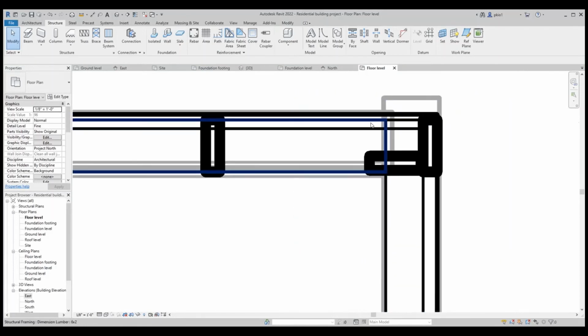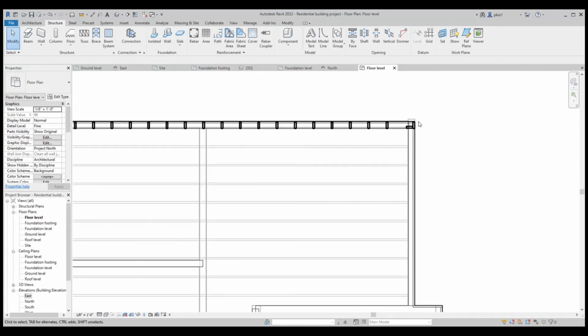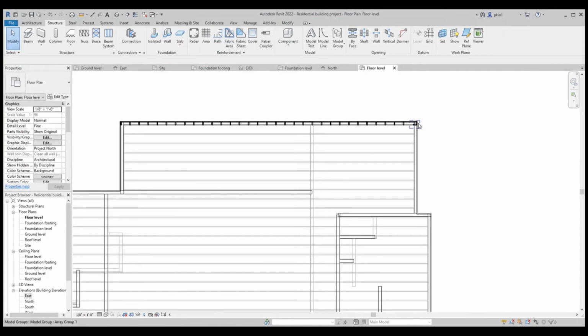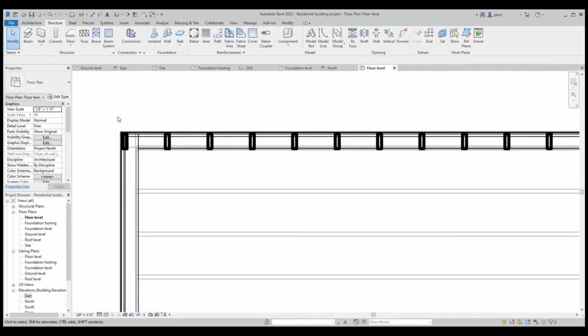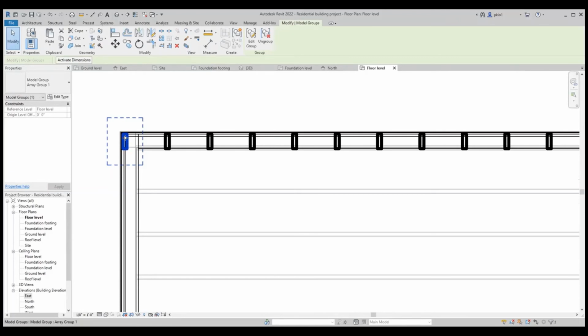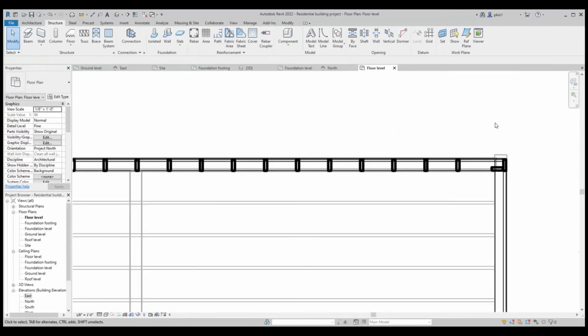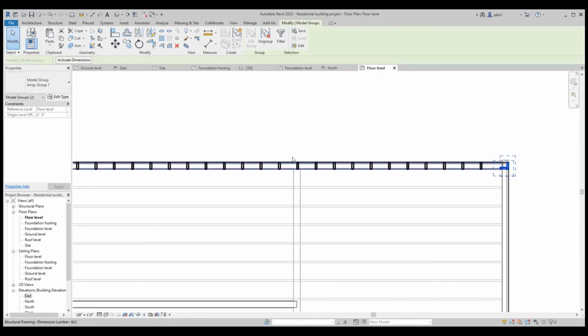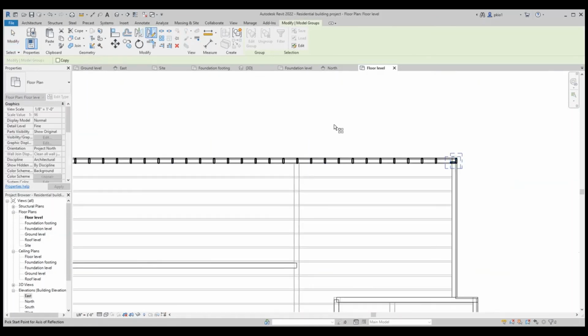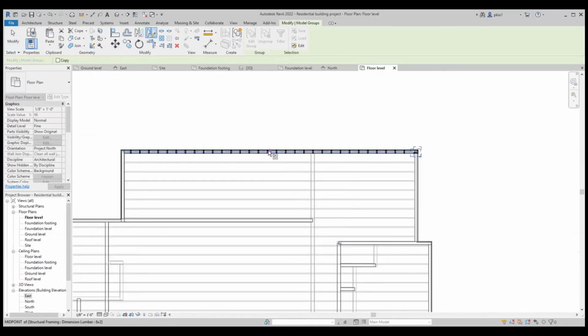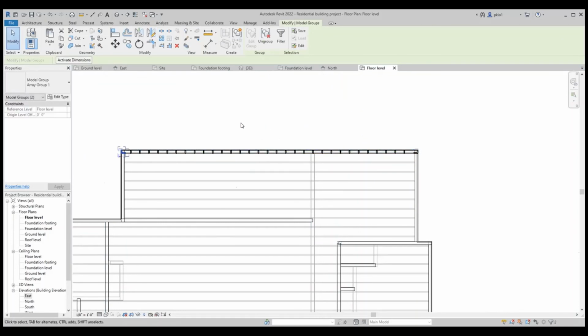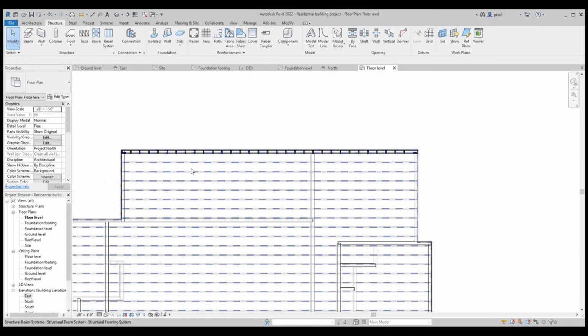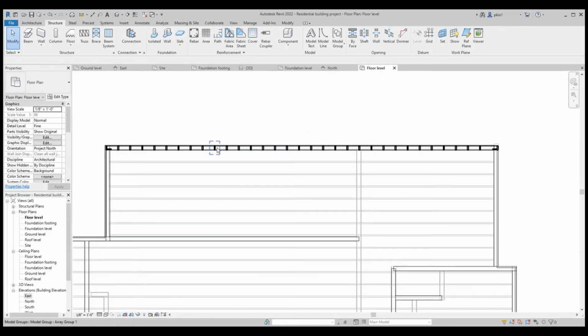This corner where we have the California corner, we can copy this, or no, we can mirror it for this edge. So I'll select it by drawing a box around it, and we select mirror, and we look for the center of this wall, which is where we have the pink triangle, and select that it should make a copy before we click again. And so we have the 2 edges California corner.